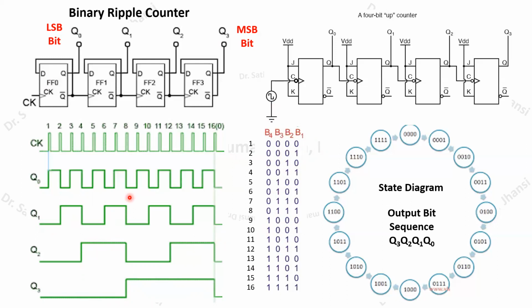So normally what we can do in this binary ripple counter while doing the experiment, either you can connect this to particular LEDs, and you can observe the sequence of glowing state of the LED, when it is turning on and when it is turning off. That state you can observe. Or otherwise, you can connect this output to the 4-channel oscilloscope and you can observe the output waveform, how these waveforms are actually changing. That way you can make the observations, right?